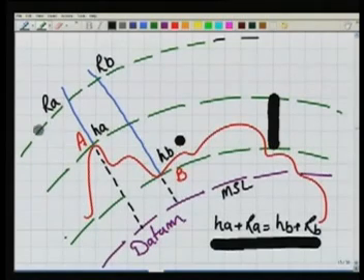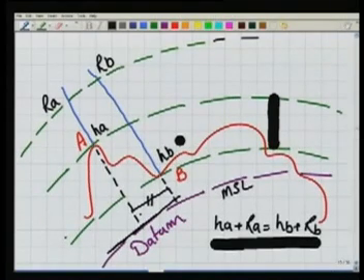So the reference surface I am using here for measurement has to be parallel to the datum. If the distance between these two is very small, then as we know, for a very small area we can consider a horizontal plane here and also establish a horizontal plane there, and carry out the same job.